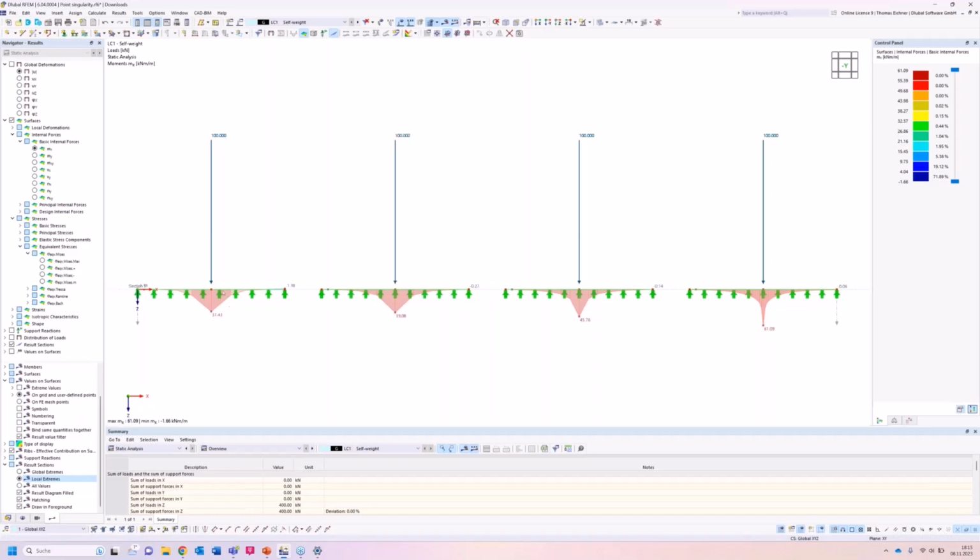For reinforced concrete, if you have a column on top or below, you would do a punching check, which treats the singularity. For this case in here, we have a nodal single load. So we could do a punching check. It's called, I think, indirect punching check. But we could also try another thing, and that's what I'm going to show you now.